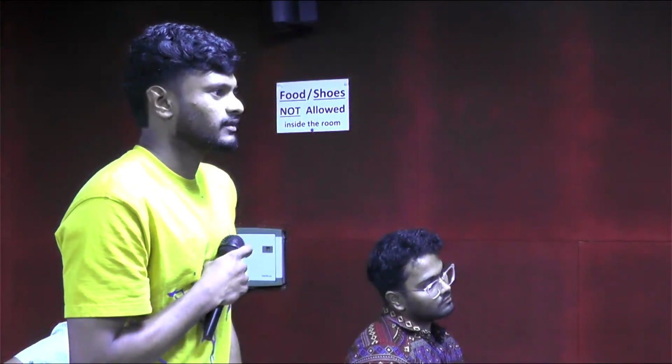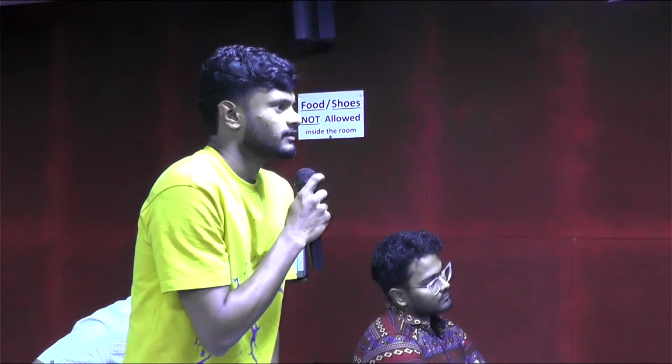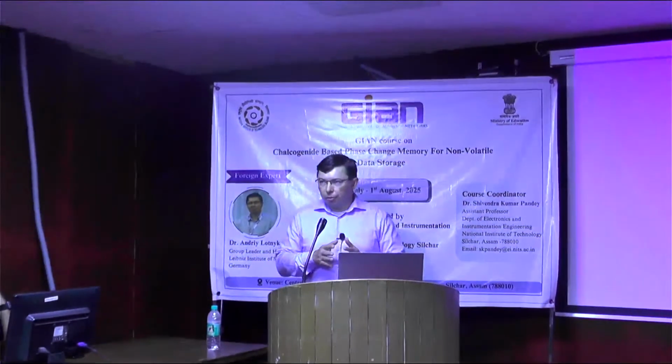One problem is that you have a bad contact to your amorphous state. You have an additional layer, and the oxide is an insulator. What do you mean, an additional protective layer we need? Yes, but that's for optical properties. If you want to measure optical properties and overcome this oxide layer formation, you should cover it by another oxide layer, which is optically transparent in your wavelength range.